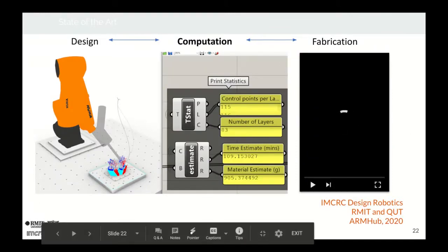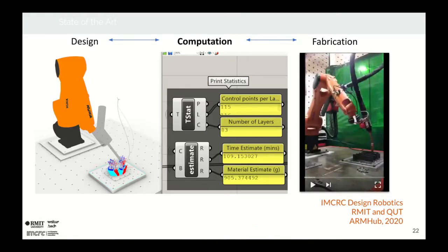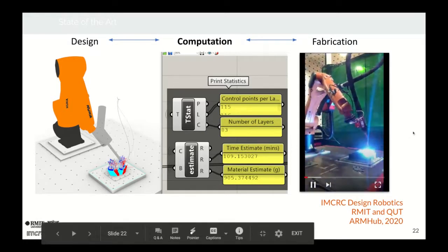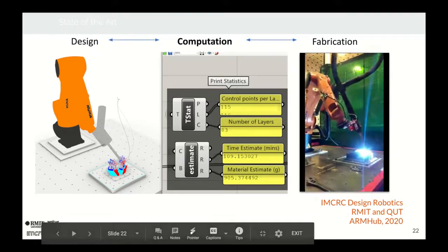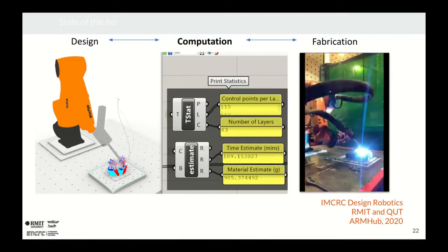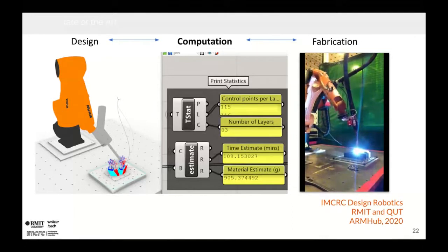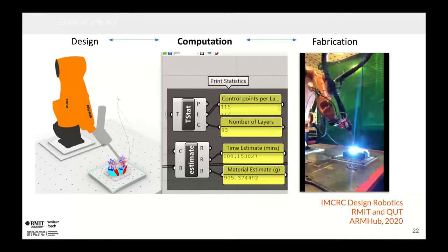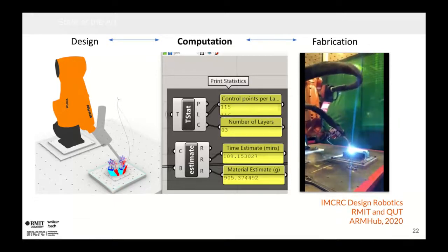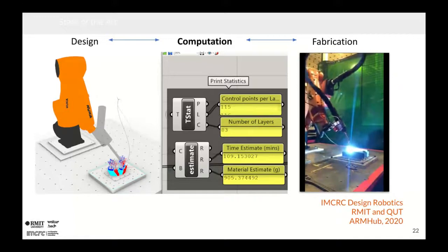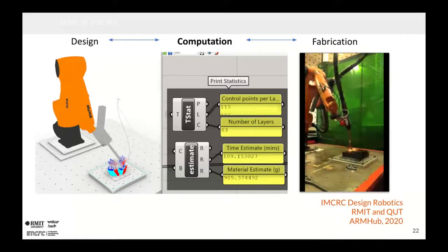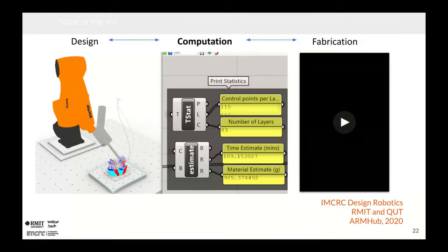It's basically looking at a tailored process for robotic welding, but it's actually called wire arc additive manufacturing. So imagine, everybody knows a welding gun, right? Like a MIG gun where the wire is fed in, and then you melt a pool and you join metal plates. But if you stack these layers on top of each other, you can 3D print with metals, and you can feed almost any material in this wire feeder, because the process doesn't really care, because metal at some temperature will melt. So you can melt aluminiums and brass and so many materials, and it's shielded by gas, so it doesn't corrode, and so forth.